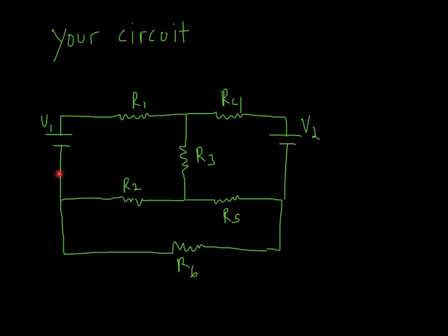All right, maybe you paused it. I paused it a little bit too. If I put a ground here, then this is effectively 0, and this is effectively 0. I might as well throw away resistor 6. It's not in there. Okay, so in some ways it doesn't make sense to ground both of these batteries. This is a case where one is at least meant to float. So in lab, if you tie one of these to wall ground, the third prong, which is the earth ground, and you tie the second one, then you shouldn't get anything through resistor 6.